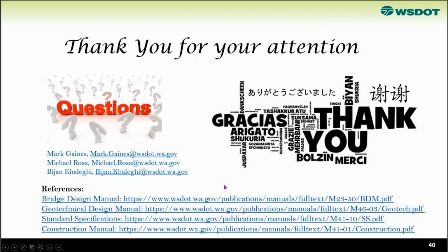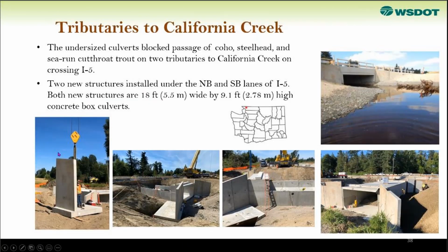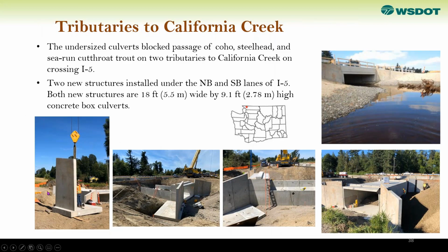Okay, the next question that came in during the webinar is, are wing walls precast also? Yeah, wing walls are precast, as shown in the last couple of slides. As you can see, the wing walls here are precast, including the precast footing in this case. We have used precast, but we also allow the use of structural earth walls in other cases too. So multiple wall types.